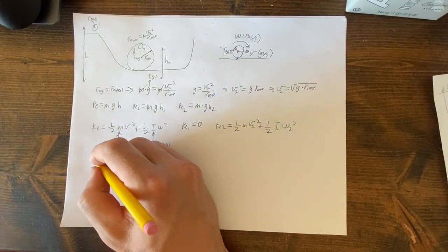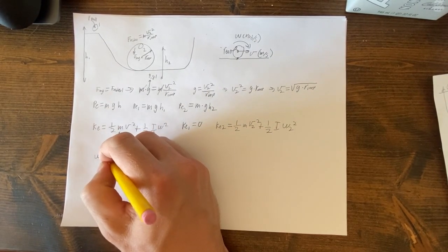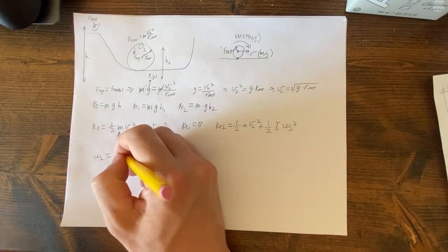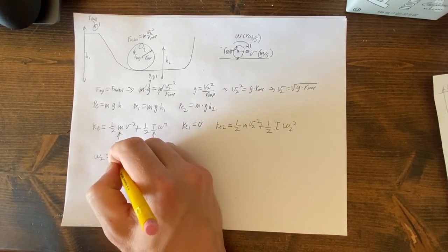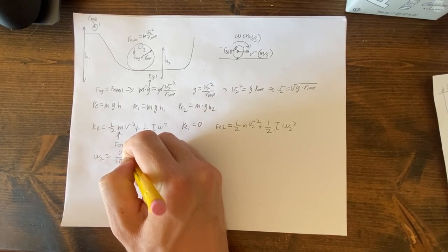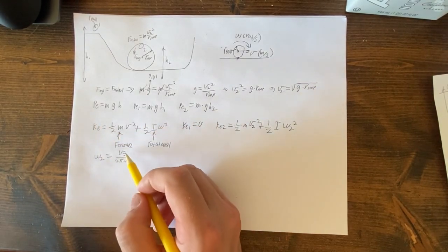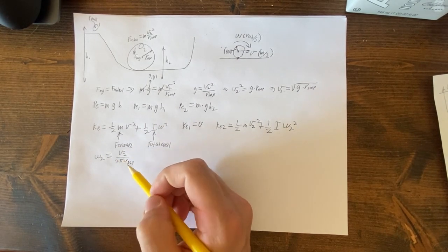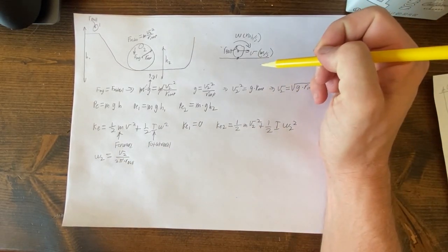So we could say omega 2 is the rotational speed in radians per second of one rotation. So that'll be v sub 2 over 2 times pi times r sub ball. Now, confusingly, as it stands right here, this is your rotational speed in revolutions per second, and as I said before, you want radians per second for your omega.